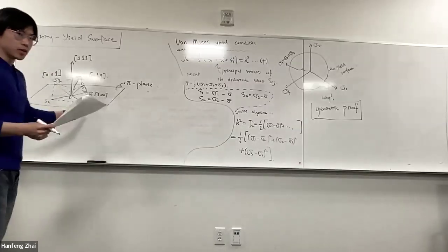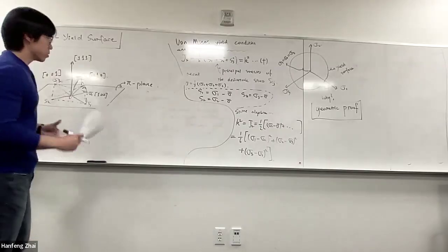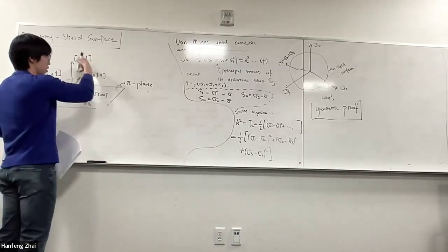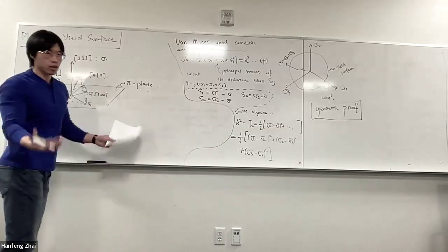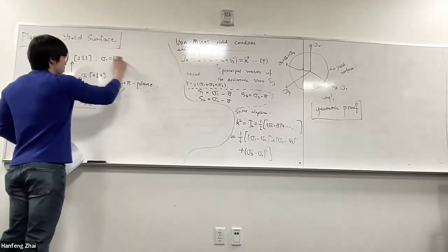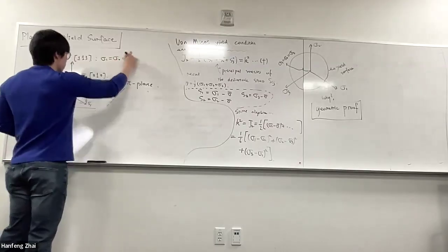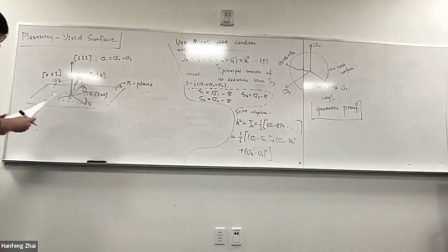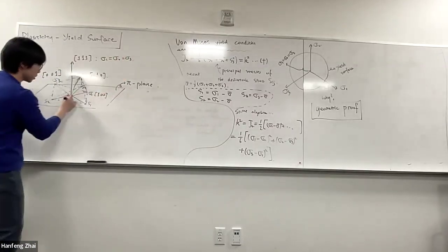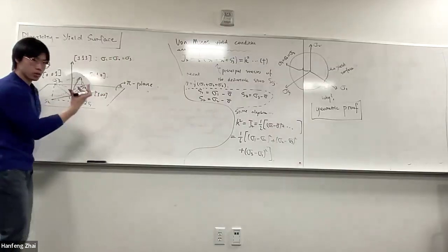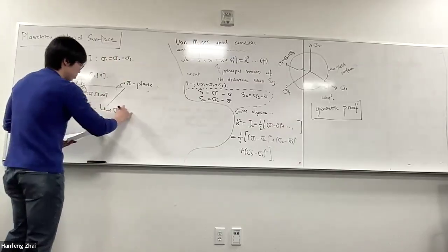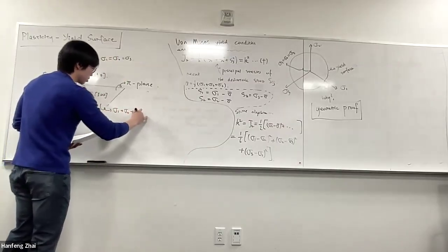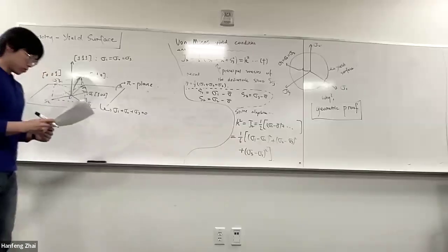And one more comment, which you probably already know the answer to: what is the 1, 1, 1 axis again? It's the axis where all three principal stress components are the same, so sigma 1 equals sigma 2 equals sigma 3. In this plane, if this is the origin of the coordinate system, then this plane signifies sigma 1 plus sigma 2 plus sigma 3 equals 0.